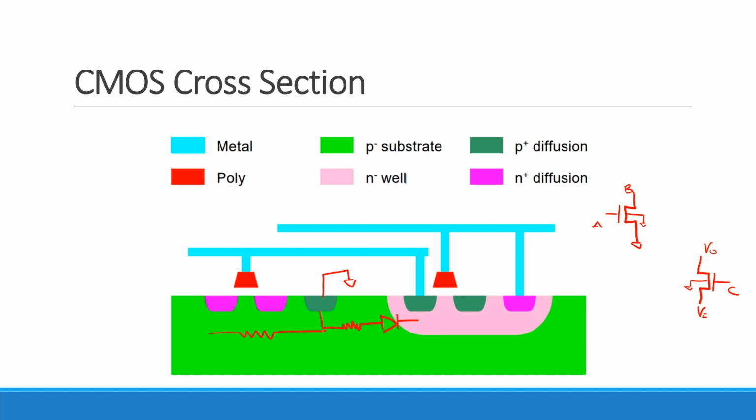And again, the only reason I mention this is because a lot of times in analog, the thing that comes and bites you is the thing that's not in your model, right? And substrate is a really classic thing that's almost never in your model. In fact, I could almost argue that PMOS transistors are in some sense even worse from that standpoint, because every time you instantiate a PMOS transistor, there are usually some components that exist in real life but SPICE never actually takes care of. So does anybody have an idea which components I'm referring to, or what they're related to?